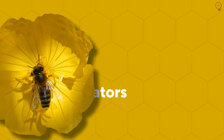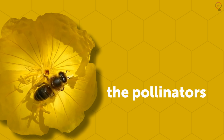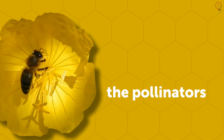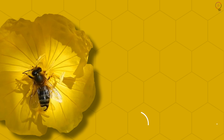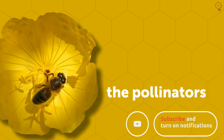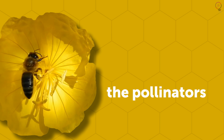Tip: artists and designers often work at higher bit depth to smooth out gradients and access more varying colors. Working at higher bit depth does require more processing, and 8 bits is the minimum depth required for broadcast quality video. Add the composition to the render queue. 1. Make the timeline panel active for the composition to render. 2. Choose composition, add to render queue.